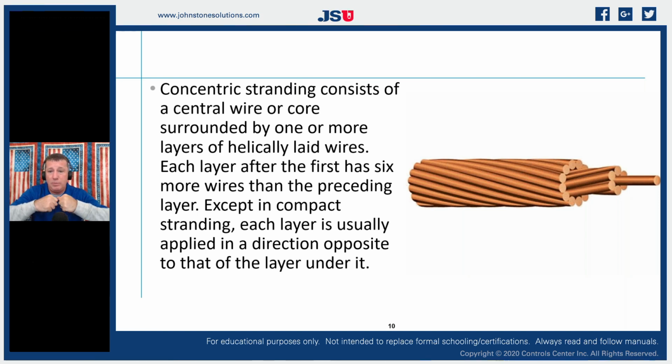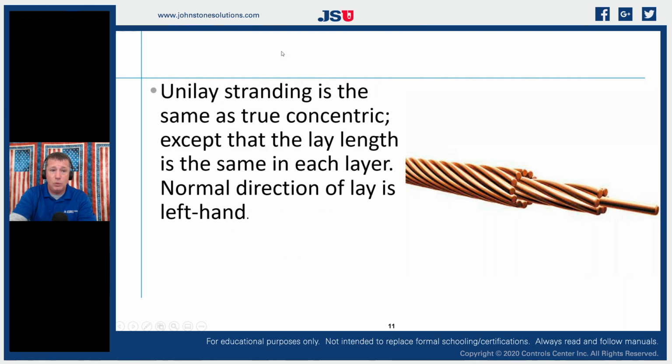So we don't want to put that extra tension along its axis, otherwise we're going to stretch the wire, and we may stretch it at a different rate than the insulation. So on a lot of these concentric stranded style wires, we'll actually use a steel core so that it has some rigidity to it. And then we'll wrap our copper around it, and it's typically in one direction.